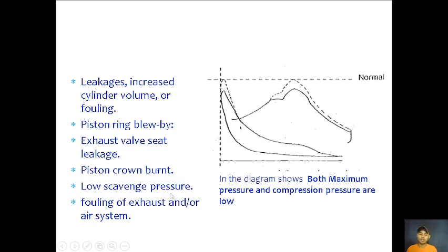Low scavenge pressure, so maybe a fouled air filter of the turbocharger, or the charge air cooler is fouled, or there are problems in the flaps of your scavenge space. Fouling of the exhaust and or air system, so both can make our compression pressure low.